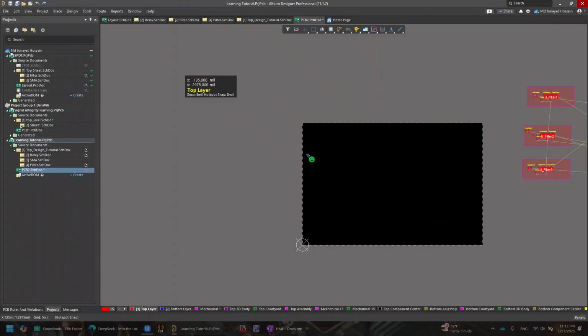Later on, you saved your work, and now you have to redefine your board again, and you start with 55 mils or something like a crazy number. You can't align your board cutout easily, and you have trouble because the grids are not aligning well. So if you work with a 100 grid to set up your board, always make sure you're using a 100 mil grid as well.